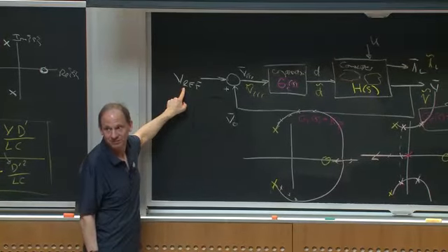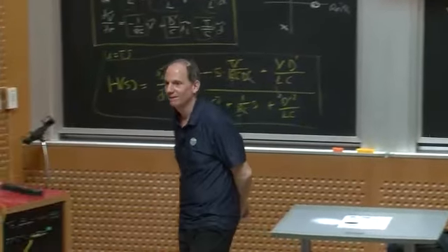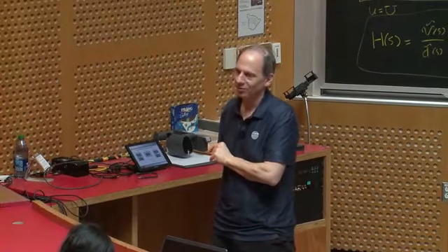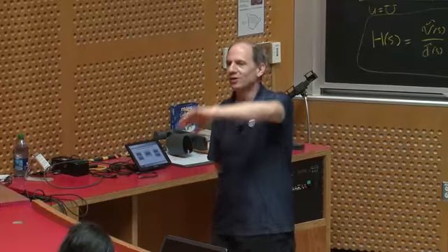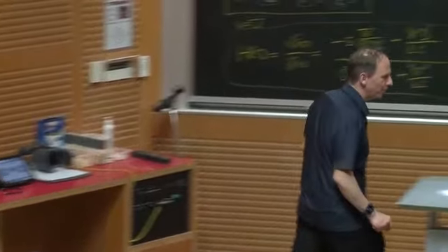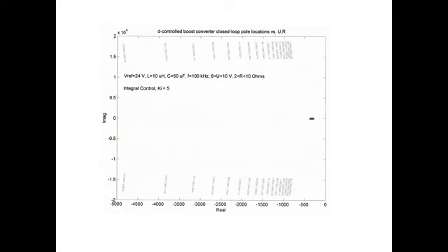Well, yeah, I guess I'm asking because the phase margin that's high is pretty heavily damped. Like 90 degrees is pretty heavily damped. Right, but the only thing that's telling you is what the dominant pole is doing. It is very damped, right? The majority of the transition will reflect that dominant pole. So the reason this looks damped is because it's dominated by this one down here.